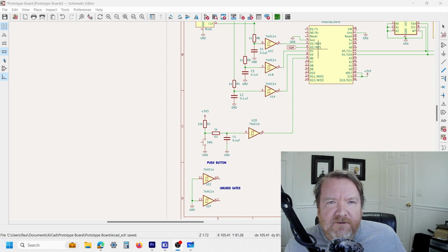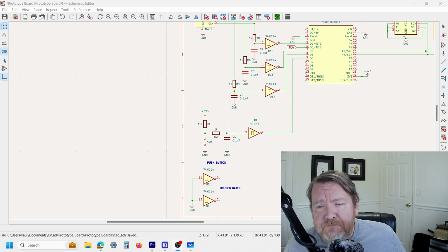You can get a microcontroller which costs maybe 2 cents. If you have to go from 2 cents to maybe 5 cents for the microcontroller to add in debounce software, it may be cheaper to add the 1.5 cents to do it electronically.